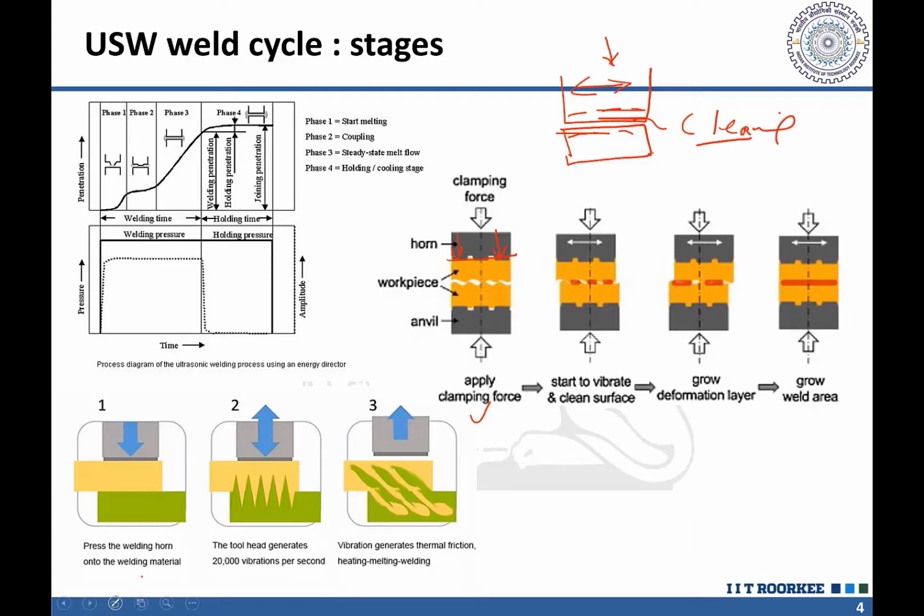That is one thing that will be happening, and the continued relative motion at the interface under the normal load will lead to increased frictional heating, and increased frictional heating will lead to thermal softening, and that in turn will lead to increased interfacial surface layer deformation.